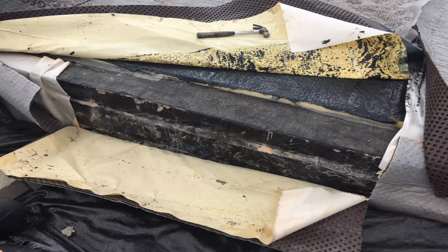We look at the waterproofing system on it. It's not continuous over the edge of that deck, is it? Over the top of the retaining wall, there's a big slot there. Okay, the top of the retaining wall itself should have been smooth, a bit like a smooth elephant's backside, if you like, a concrete haunch, to allow the waterproofing system to transition over the top of it and down the outside of the wall. Is it? No, it's a dog's dinner. Okay, so there's problems there.